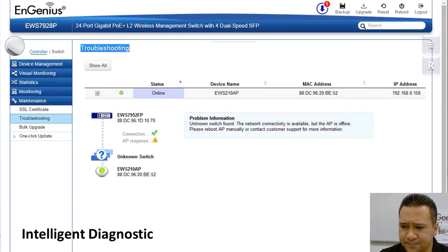If you go to the switch function, there is also a troubleshooting page where you can even physically do some measurements on the cabling, and check if the cable and the wiring are correct or not. You can already see the estimated distance, the length of the cables, and check on the switch side if there are some problems in the network.